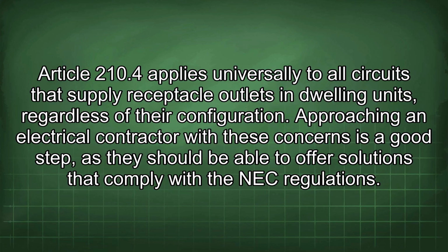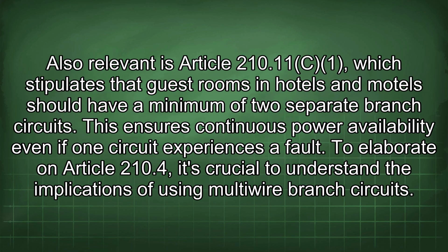Approaching an electrical contractor with these concerns is a good step, as they should be able to offer solutions that comply with the NEC regulations. Also relevant is Article 210.11(C)(1), which stipulates that guest rooms in hotels and motels should have a minimum of 2 separate branch circuits. This ensures continuous power availability even if one circuit experiences a fault.